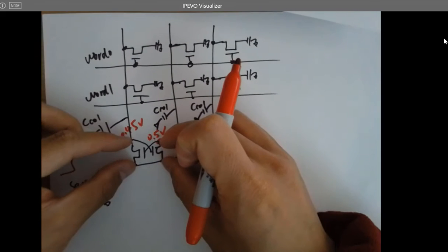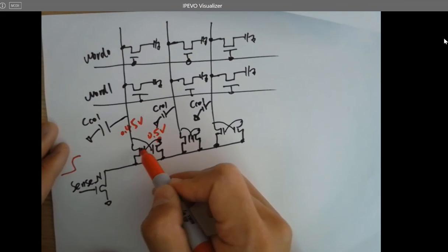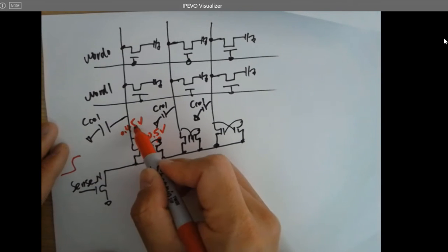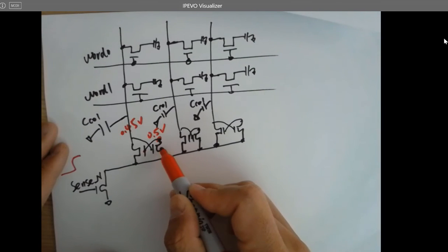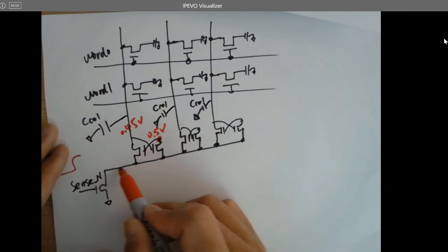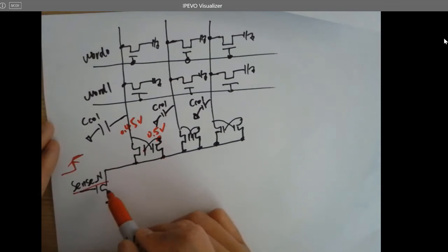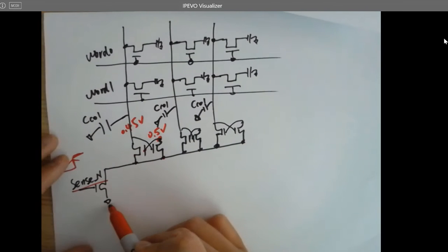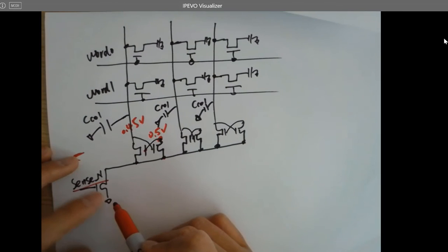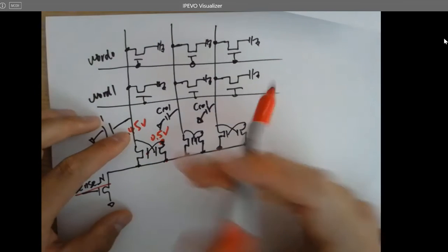So these two transistors, this is 0.5. It's going to turn on this guy, right? This 0.45 volts is also turning this guy on as well. However, the sources of these two transistors are being shorted because this is on. You are sensing, just give a rising edge. So both of the two sources are being shorted to the ground. So what's happening is they are both on, but they're competing with each other.